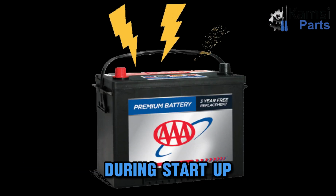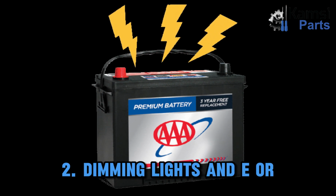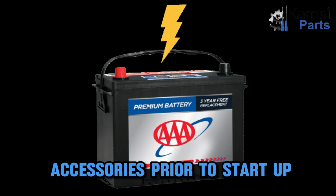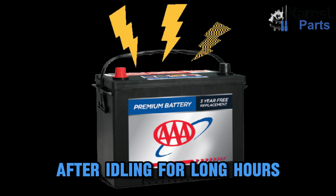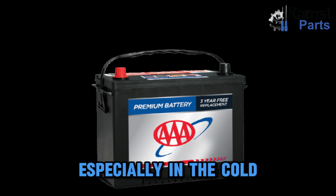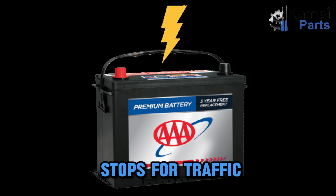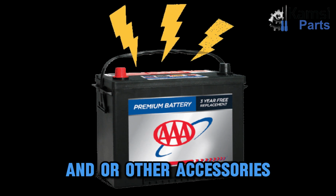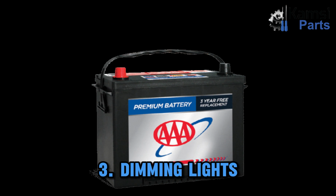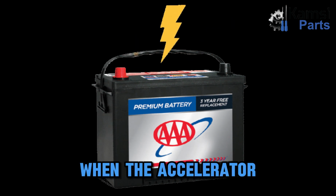During startup: 1. Three or more turns for ignition. 2. Dimming lights and or accessories prior to startup. 3. Greater difficulty in startup after idling for long hours, especially in the cold. During driving: 1. Slightly rough stops for traffic. 2. Intermittent shutdowns of the radio and or other accessories. 3. Dimming lights and or accessories when the accelerator is pressed.